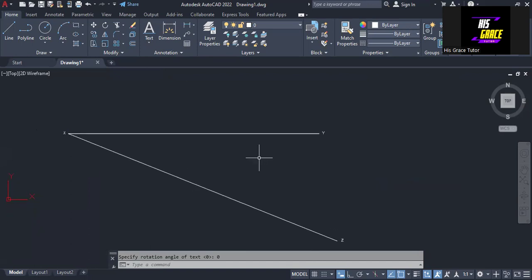So the next thing that we are going to do is divide this line XY into a number of equal parts, or into a given proportion. Based on the ratio of sides that we are given, 3:5:7, if we sum the 3 values together, that will give us 15. So we are going to divide this line into 15 equal parts. I'm not going to use an arc to do the division of the line, but I'm going to do it this way.